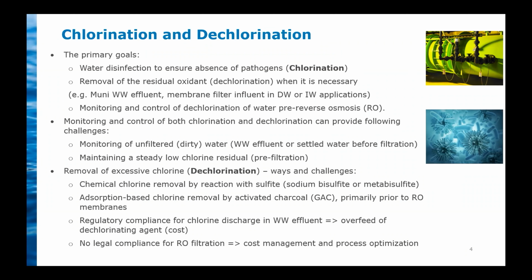Typically, a total of 1000 ppm hours of chlorine can increase salt passage by 50%, as an example. And we'd like to always maintain a steady low chlorine residual. Also, an excess of chlorine will cause premature biofouling of the filters, and the excess of chlorine may damage the membrane, shortening their lifetime.